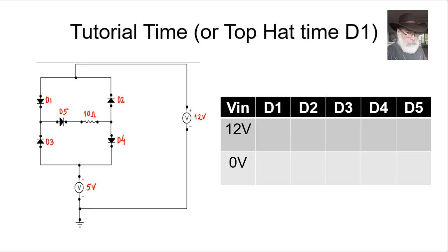All right, so we will have current that will be flowing like this, right? The current is flowing like this through the external circuit, right? When that current arrives at the node on the top, it tries to go through D2, and that will only achieve opening D2. So D2 is now open, so that current has no recourse but taking the path through the right, and in doing so will close diode D1.